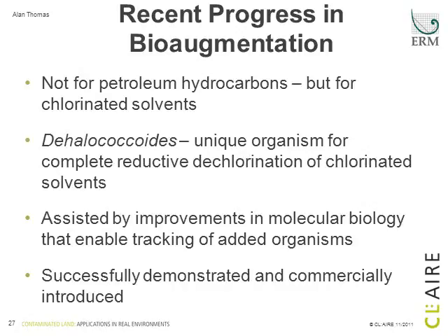Recent interest in bioaugmentation has been in respect of chlorinated solvents. Dehalococcoides is a unique organism that's required for the complete reduction of chlorinated solvents, and the interest in bioaugmentation has been stimulated by improvements in molecular biology that allow better identification and tracking of added microorganisms. This technology has been successfully demonstrated and is commercially introduced.